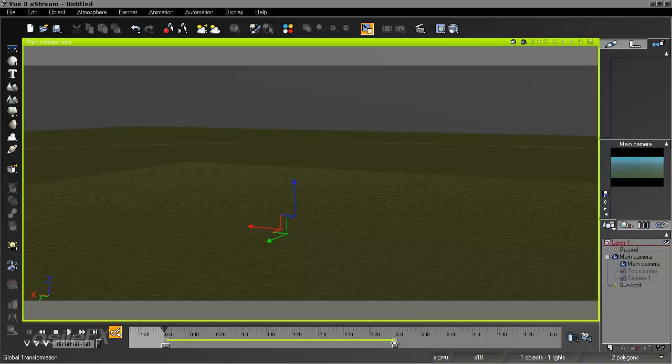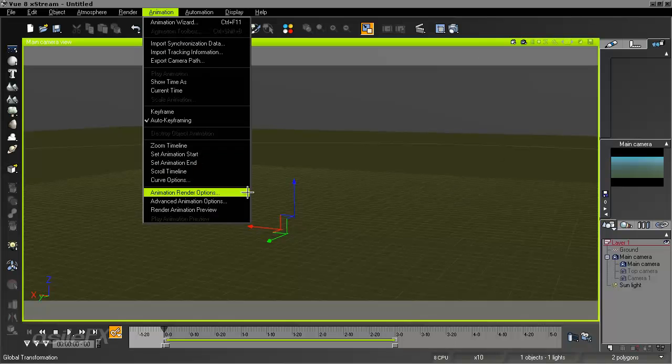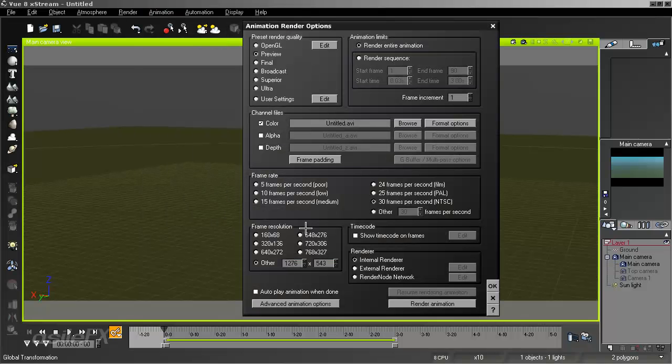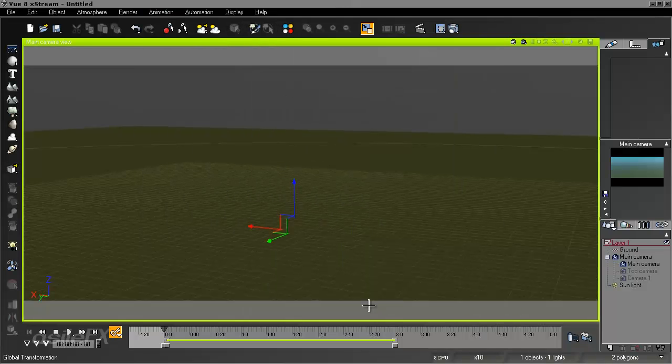Also, the animation is exported, and you may have to change your frame rates. So if you go into the animation render options, get it at 30 frames per second, and we do have a total of 90 frames in the LightWave scene. That's my default instead of 60, which is the normal default. So that is 3 seconds, and transferred over. So if we had any camera motion, that would also export all of the keyframes. So that is another available option.